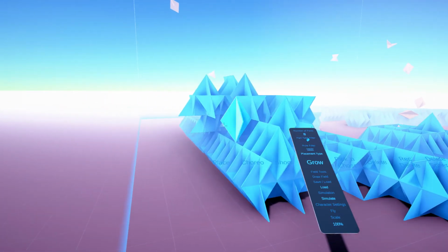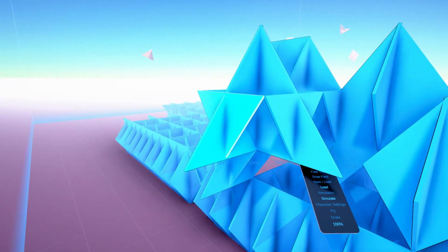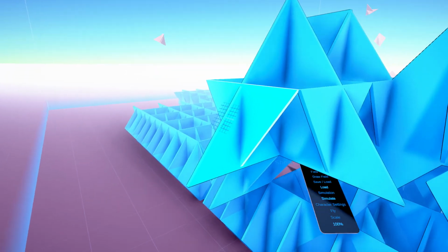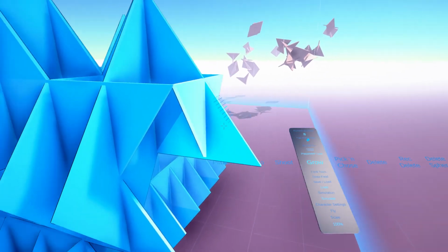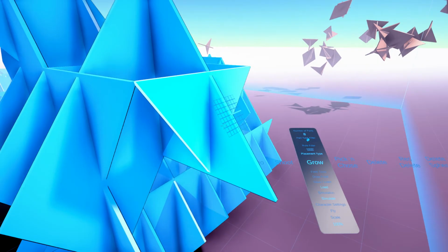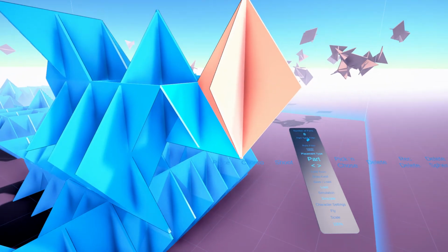And afterwards, there would be grow. And grow makes a lot of sense to do small starting aggregations that you load back in Wasp, or to really go in there and do the minute stuff. So I can click on a part where I want to aggregate on. It will show me the open connections here. And I can choose one. It's displayed with this plane, like a Grasshopper plane. And I can click the one that I like, and it'll spawn a part that fits there. And I can now, with left and right on my keyboard, change what part I want to have there.